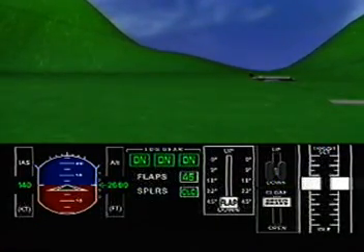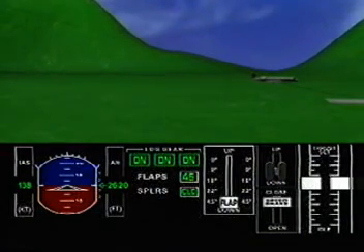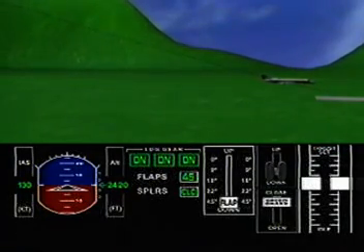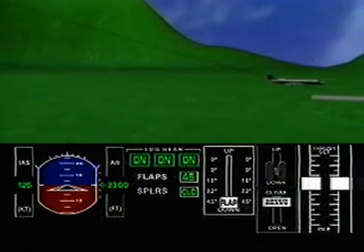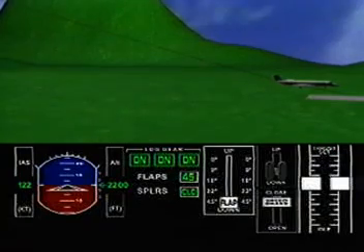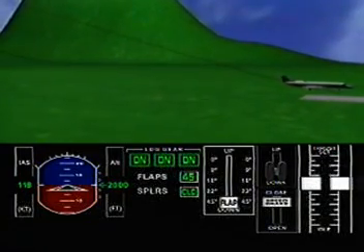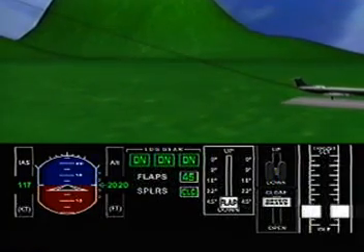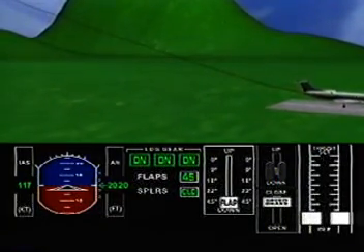This is your landing configuration, which must be established at 3 miles from the touchdown point. Upon setting flaps to 45 degrees, adjust power to maintain at least VAPP and cross the runway threshold at VREF. Use the proper technique to touch down in the 1,000-foot landing area.